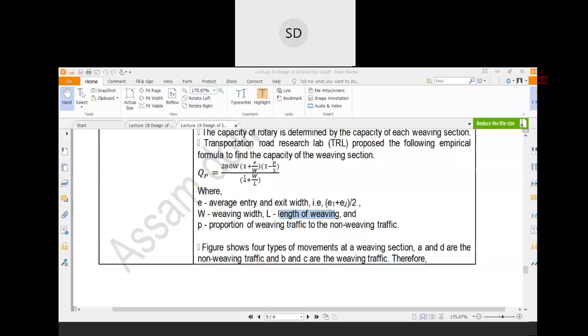In that case, it is okay. For some intersection, suppose you find that it is 3500 vehicles per hour or 5000 vehicles per hour. If it exceeds 3000 vehicles per hour, the capacity of the intersection is basically overflowing.